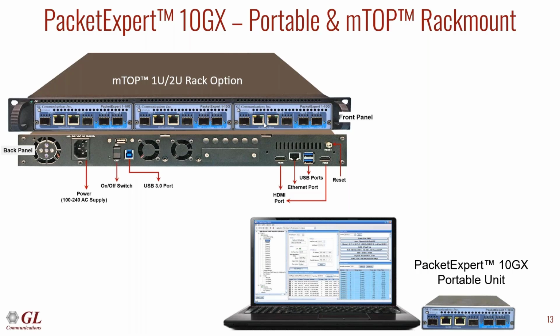And so if you need lots of ports, we've had customers that have come to us and been like, we need to test a 24-port gigabit switch. Can you do that? Can you test all 24 ports simultaneously? And the answer is yes. We can put 6 of these PacketExperts, each with 4 ports, into a 2U chassis, and plug directly into all 24 ports and fire away.